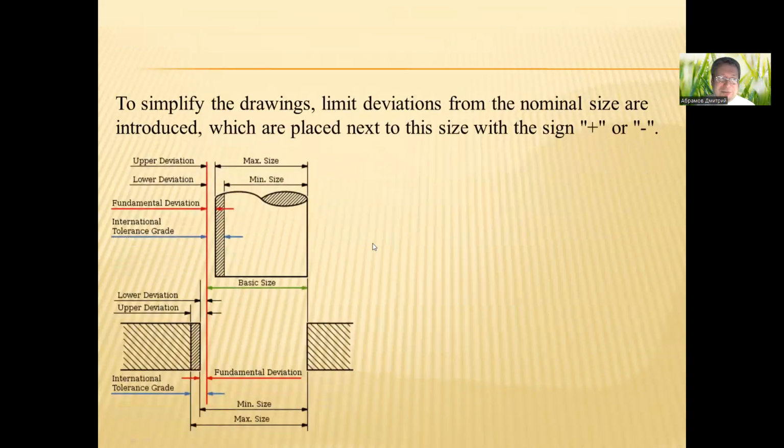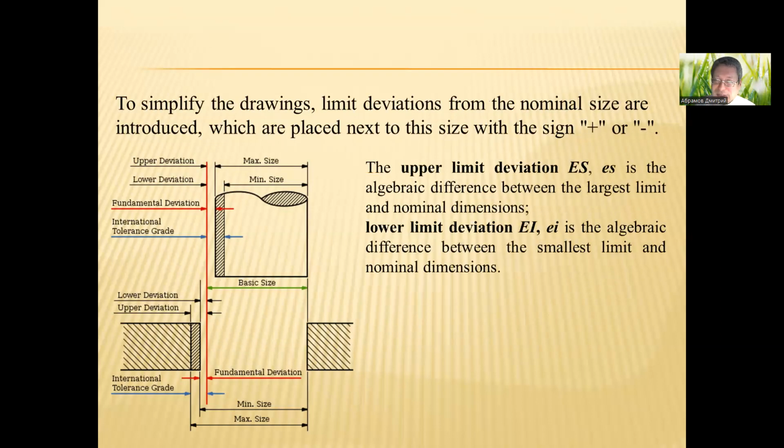To simplify the drawings, limit deviations from the nominal size are introduced, which are placed next to this size with the sign plus or minus.